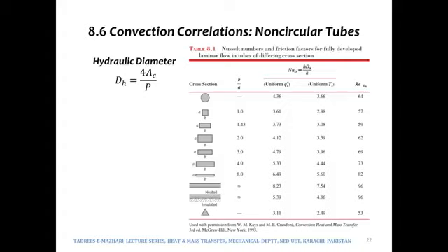So of course the hydraulic diameter of a circular pipe would be D, but for other geometries apart from circular cross sections, what it does is that it provides an equivalent diameter, equivalent to the circular ones, if the geometry that we have in hand is non-circular. So this is how the hydraulic diameter is used, and this is what it is used for.